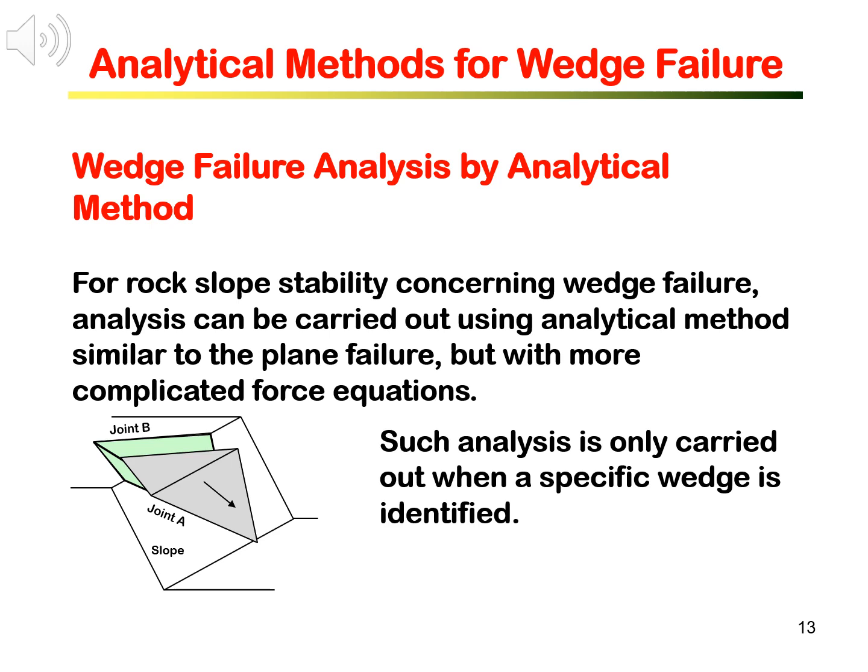It can no longer easily simplify into 2D force diagram and the force equation. Force equilibrium is much more complex as it involves two planes. In fact, limit equilibrium analysis is only carried out when a specific single wedge is identified for stability analysis.